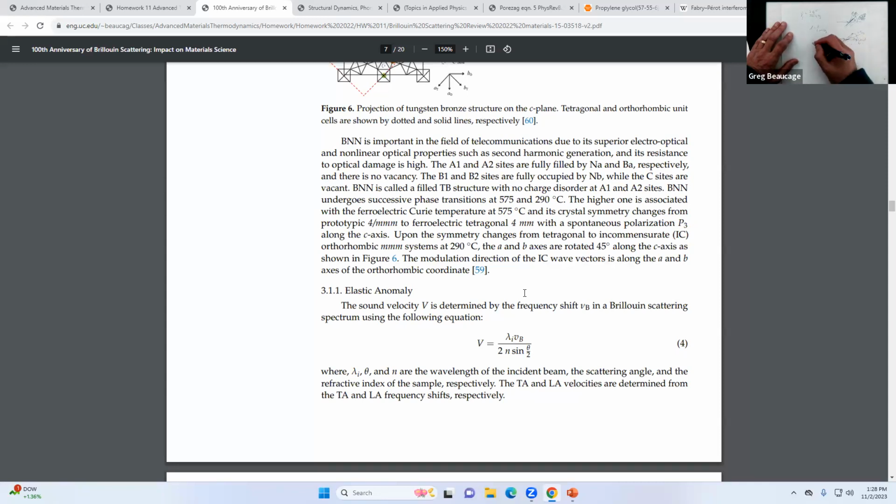You plot XRD, you do intensity versus 2 theta, you see a bunch of spikes. They say it's FCC. So the 2 theta comes because you have this reflection plane, and you say that's 1 theta, that's 2 theta. It's like a mirror. So you shine in, you get the reflection, even though it's not actually a mirror.